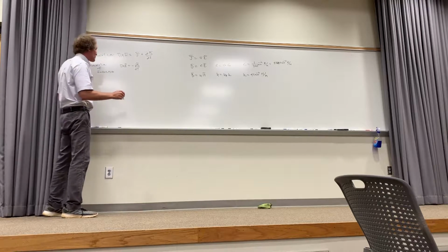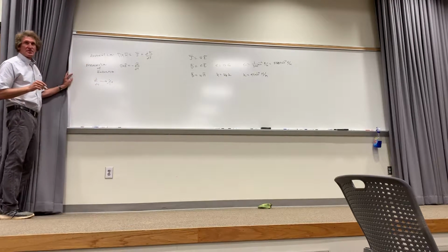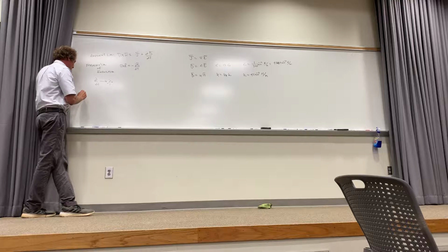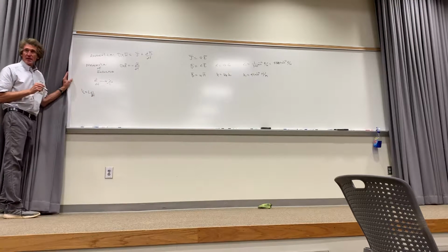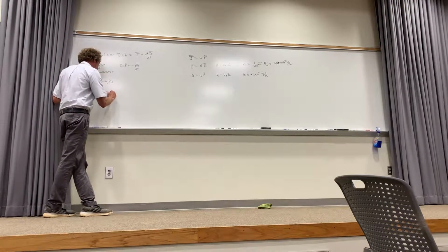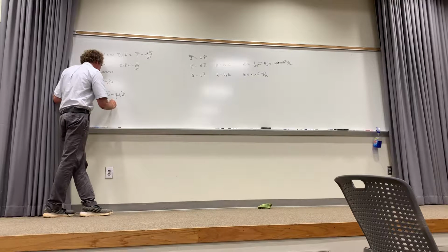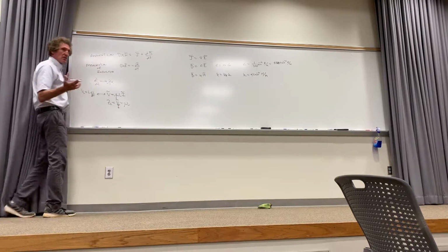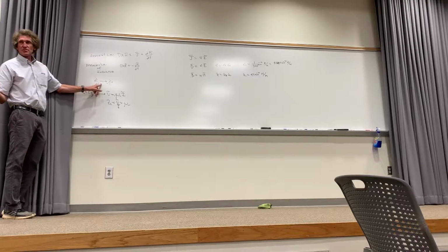When you have a derivative in the phasor domain, d/dt translates as j omega. Let me just give you an example of this. Do you remember current relationships with inductors? The voltage across an inductor is equal to L times di/dt. Do y'all remember that, class? L di/dt is the voltage across an inductor. Well, in the phasor domain, the voltage across an inductor is j omega L times the current in the inductor, or really the impedance of an inductor is simply V over I, or j omega L. Most of you remember that, right? In circuits. And you'll have to know this well. So anytime there's a time derivative, it just brings out j omega.